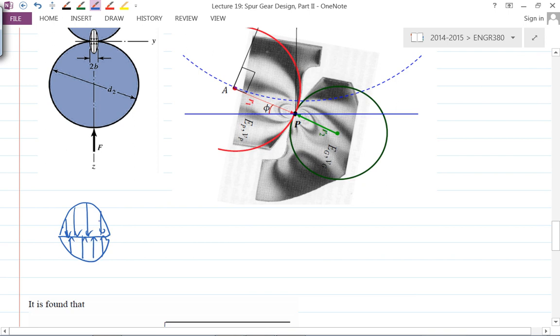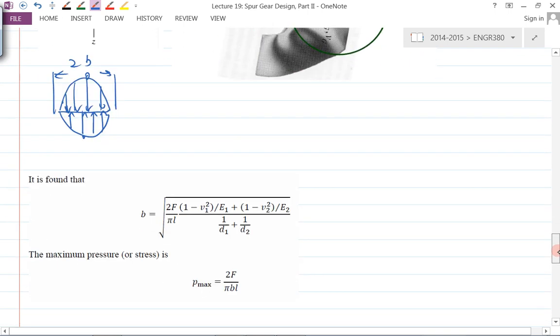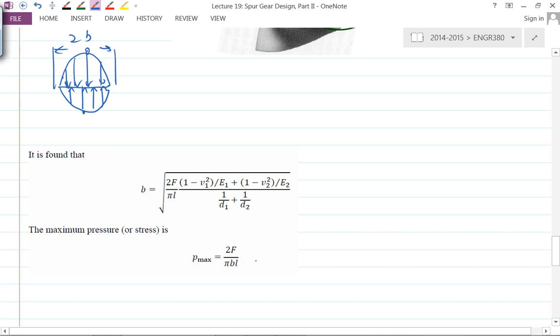Okay, yeah. It's not even, it's not constant. Somewhere maximum over here and here, right? Yeah, that's right. The distance, this much distance here, 2b, is supposed to be how much material has been flattened because of the compression, right? 2b, okay? Yeah. So without too much work here, we can calculate the maximum stress or pressure, which is at this location here, the P max.